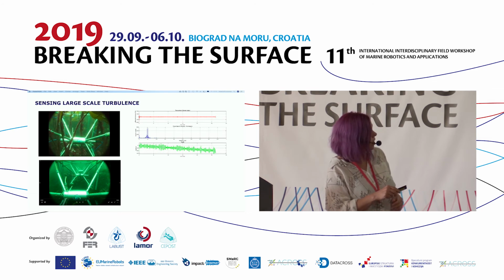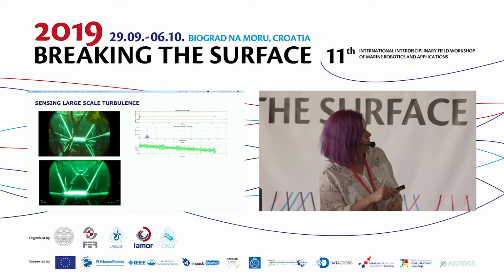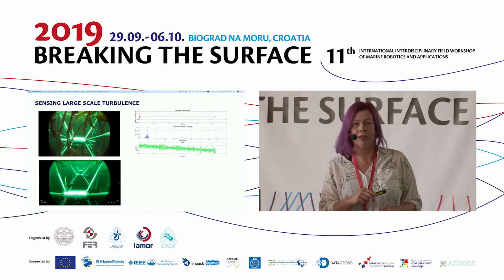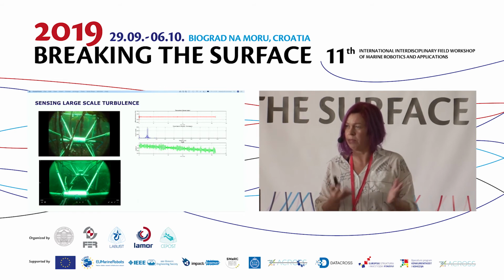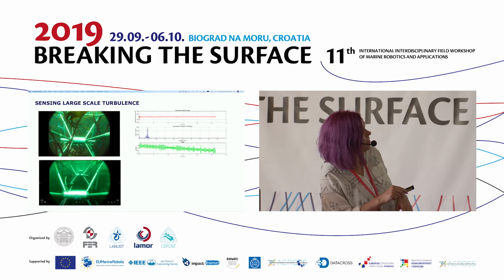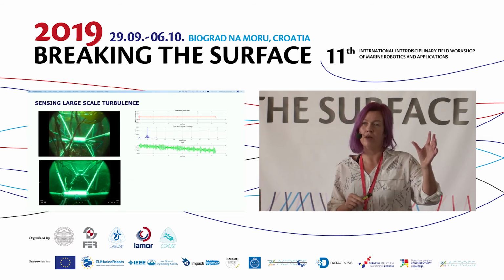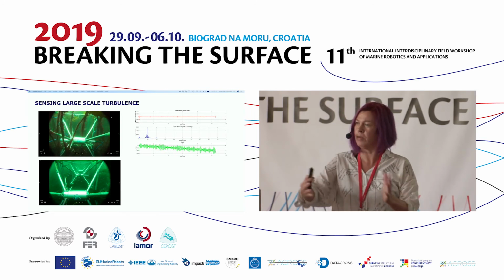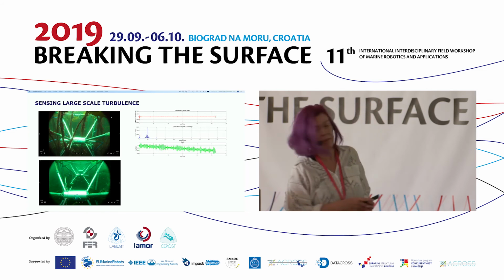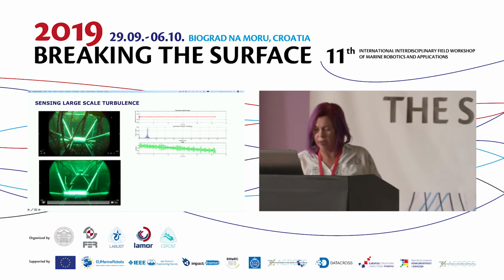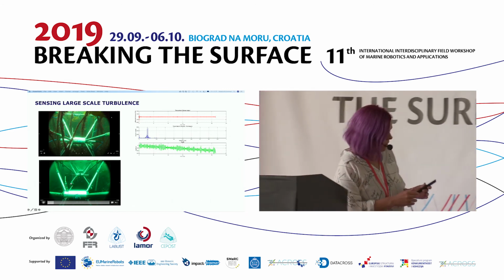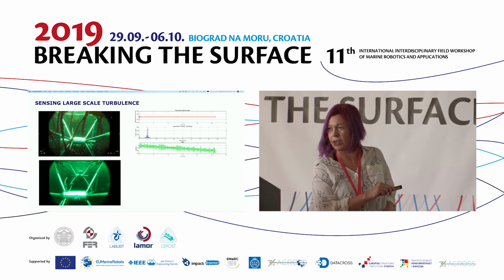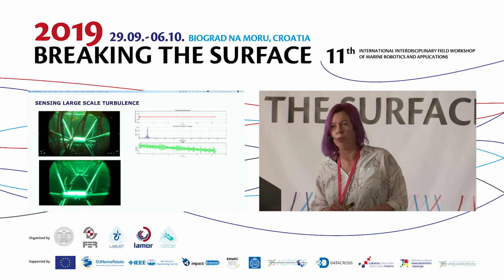And if you now resolve these sensor readings in the frequency domain, you could actually figure out the frequency of the waves coming in, the largest waves. And you can also figure out that there are very few higher order harmonics. So the waves that make an impact on the ocean floor are only the biggest ones. And here is just a comparative example where the tidal flow is very, very, very high. You could see here a little stem, and it's vibrating hysterically already. So it's almost saturated, and this flow is about 4 meters per second.